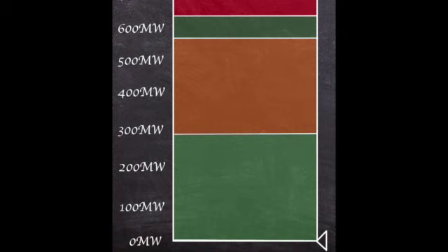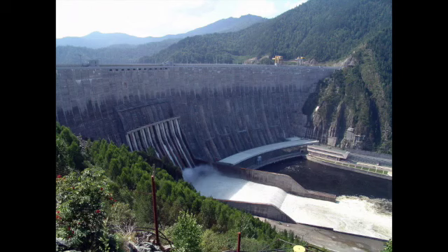The power station operates between the bands of 0 and 350 megawatts and 550 megawatts to 650 megawatts. If it is outside these bands, that is what causes the vibrations to occur. The input flow rate also changes depending on the height of the water behind the dam, which changes throughout the year.